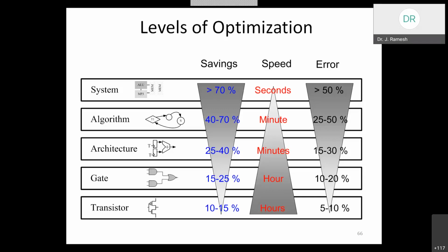So you know that static 0, static 1, dynamic results, etc. These hazards are to be avoided, and that can be done with the help of appropriately repositioning the latches, so that we can eliminate these hazardous activities. And we can go for pre-computation logic also. We'll see pre-computation logic in detail while seeing each of the levels of optimization.